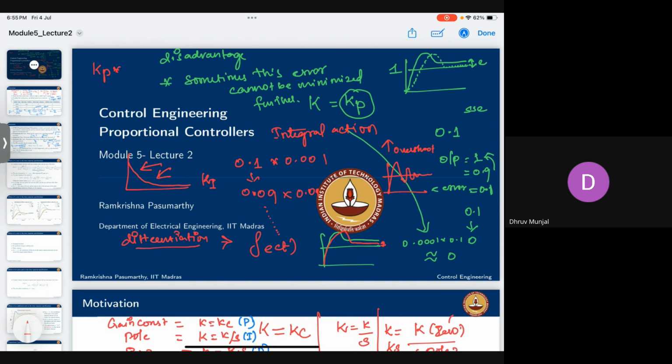That's where the differentiation comes to the rescue. This differentiation will bring down the overshoot value. It won't make it go too much. Even if your integral gain is too much, it will just hold the gain value or bring down the gain value, whatever value the integral part is taking it up. But the disadvantage of this is that it makes the system sluggish sometimes.